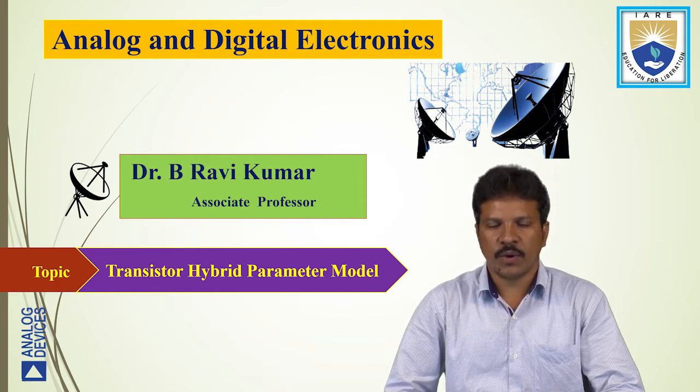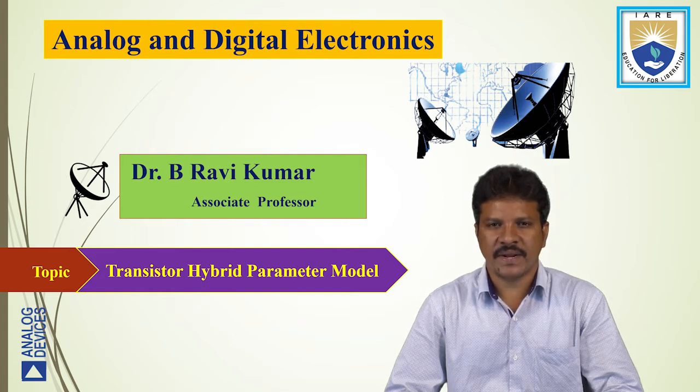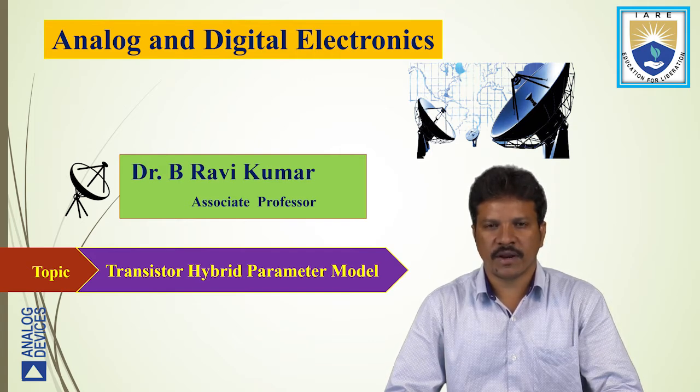Whenever we connect any two-terminal device like a diode in a network, either in forward bias or reverse bias, we can draw an equivalent diagram for the diode: a voltage source in series with the internal resistance small rf, in series with the diode symbol. When we replace the diode with these three elements, we can accurately analyze the current flow in the network or the voltage drop across the diode and the internal resistance by using this diode equivalent circuit.